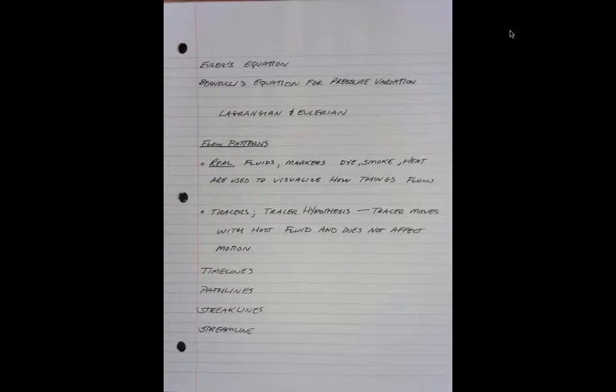So if you could attach a blinking LED to a fluid particle and then had a video screen that could keep track of the blinking LED over time, the path that LED draws would be a path line. A streak line is the trajectory of many particles that all pass through some common point in space. A streamline is a line in a flow field that's tangent to velocity, and no flow can cross a streamline. So streamlines have some important, both practical and theoretical implications.